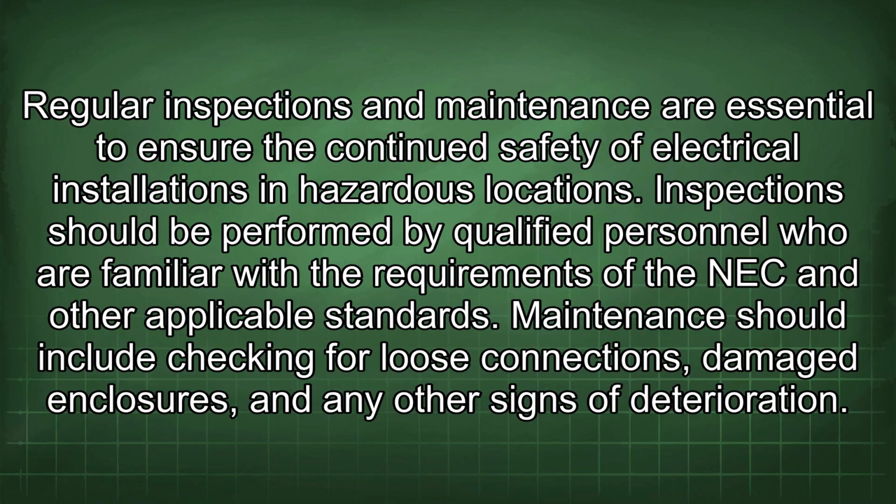Inspections should be performed by qualified personnel who are familiar with the requirements of the NEC and other applicable standards. Maintenance should include checking for loose connections, damaged enclosures, and any other signs of deterioration.